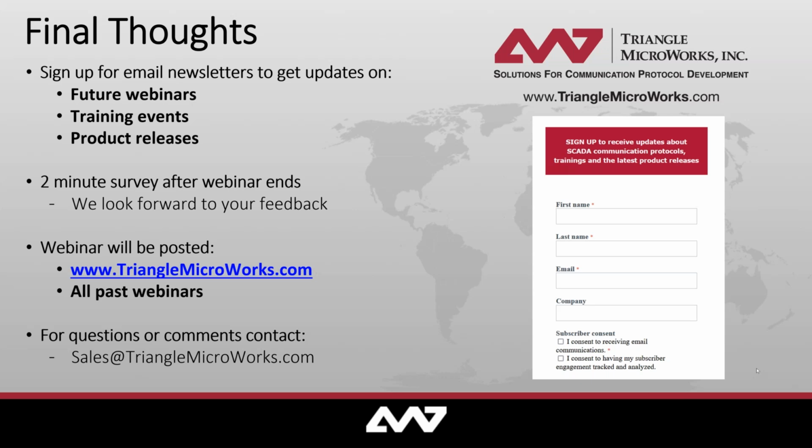If you are running DTM like I did today and Test Suite Pro like I did today, MMS, if you open up Wireshark, you'll see that. If you are running GOOSE, you'll be able to see that. We've tried to provide tools such as the protocol analyzer, GOOSE viewer, report viewer, and stuff like that, that can actually go and make the signals that you might see in Wireshark a little more human readable. But if you really need to get down to the specifics of it, absolutely. All of the traffic is running off the same source code library that are in devices all around the world. So anything that you want to see, sample values, GOOSE, MMS, that's all out there on Wireshark.